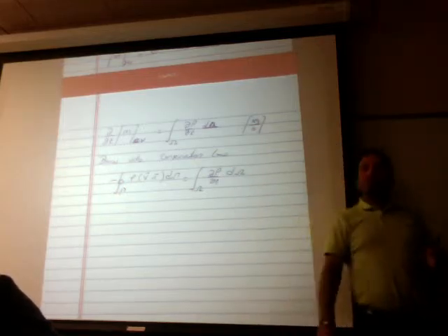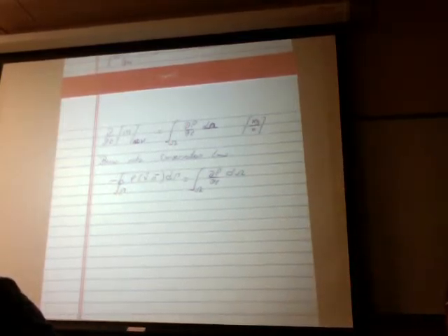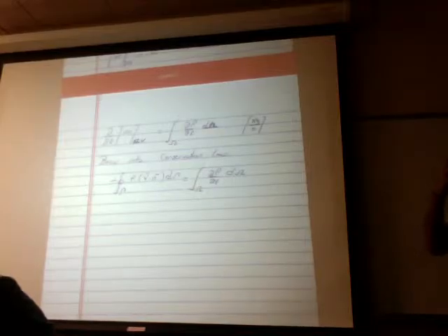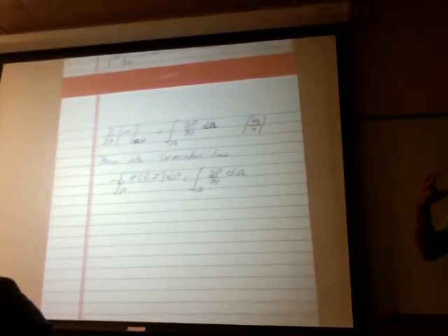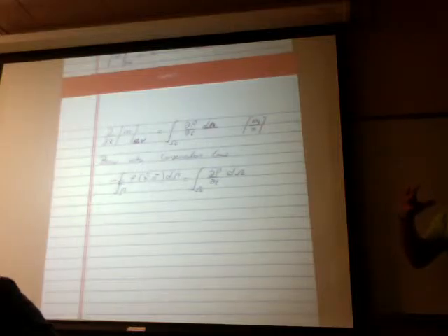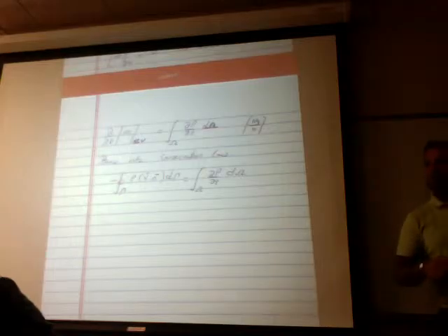If the fluid is compressible, you put fluid in. The control volume is not changing in size or shape because it is a control volume after all. But you're putting mass in, and then that mass accumulates in the form of density changes, and at some point it's going to comply and leave through the other side. But the instantaneous mass flow rate coming in is not equal to the instantaneous mass flow rate coming out because the flow could be compressible.